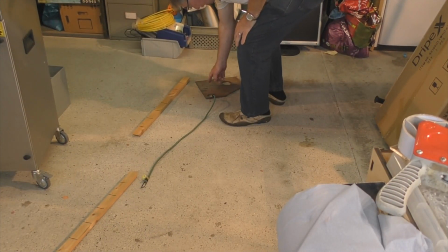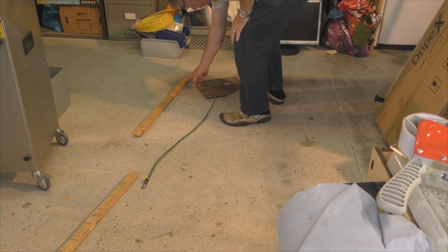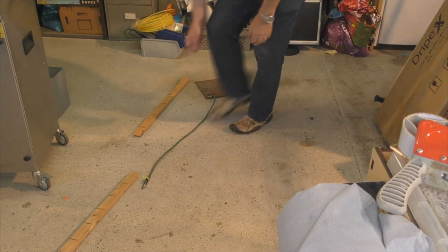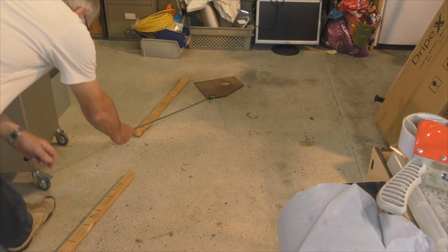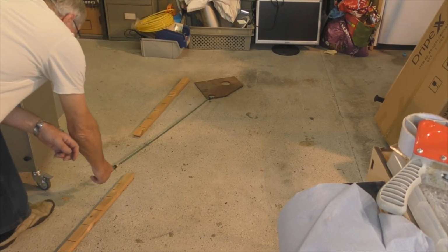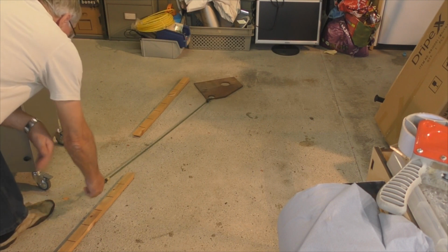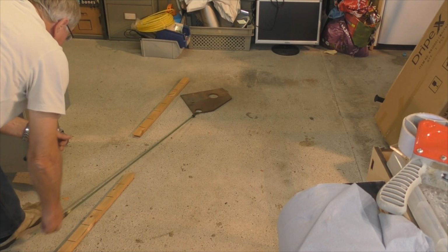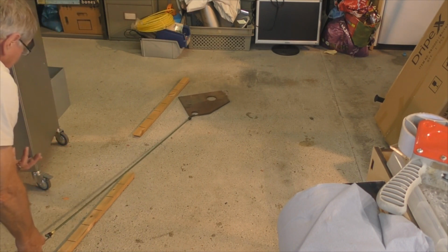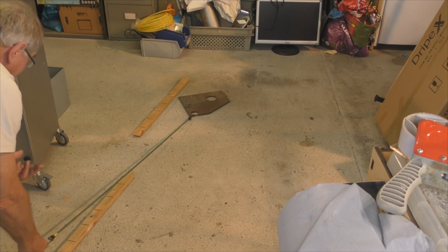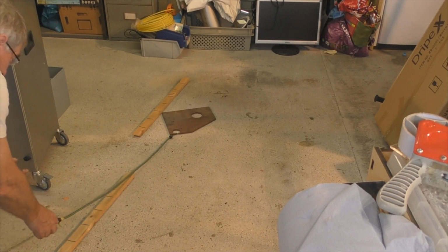If I want to move 5 steps, basically what's happening, if you can imagine an eye on here watching these marks, is what the rotary encoder is doing. So although the stepper motor will be issued with a number of pulses that it's expected to give, say 50 pulses, it'll give a pulse, a pulse, a pulse, and it'll say, right, okay, I've had enough pulses now, but I'm still not where I want to be. I want to be at 5 marks, and I'm only at 3 marks. So let's carry on. And now it says, okay, I've got there.